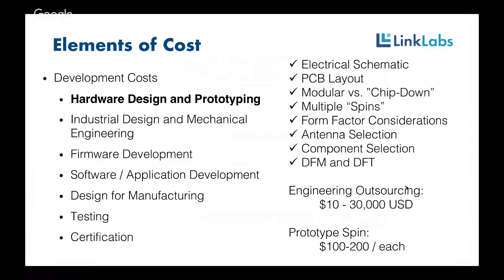Antenna selection. These are wireless devices that some need to connect over very long range, and you don't want to give up a lot of performance right from the get-go by picking a poor antenna. Little chip scale antennas, they may look great when you're browsing through DigiKey, but sometimes their performance is really going to eat your lunch. I already talked about component selection.